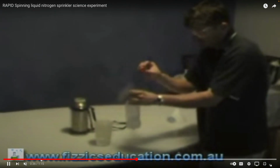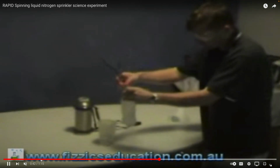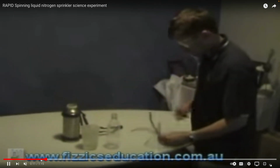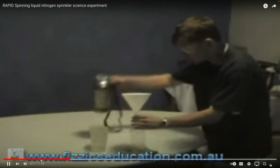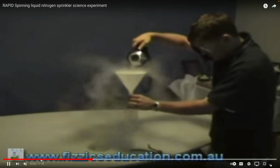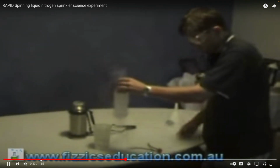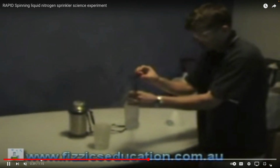So one would be linear impinging flows on wind turbine blades, to turn them into rotational motion. Flows through a turbine, so linear flow of water from an upstream dam with high velocity, gained exchanging potential energy in the upstream portion for kinetic energy downstream, and then converting that linear kinetic energy to rotational energy, which will run a generator. That is just an electric motor backwards, where you power the rotor and use the armature to generate electricity rather than putting electricity in it to generate motion.